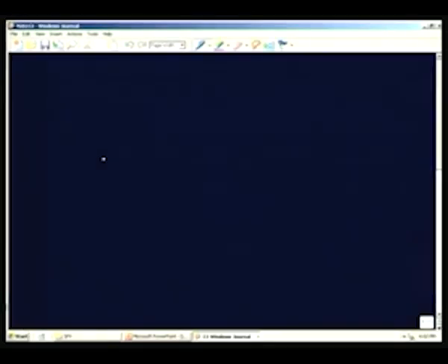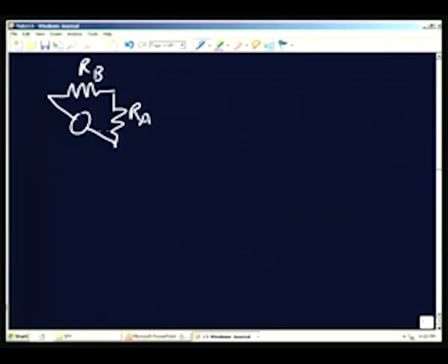I am going to take a look at the arrangement. So, in the first case, this is RB, let me just call that RA and RB, and the milliammeter is here to indicate the balance. I am just drawing a simple sketch corresponding to what we had. This is the resistance which is going to be varied, RS we will call it, and here we have the RTD with the 4 lead wires, this is the PRT.